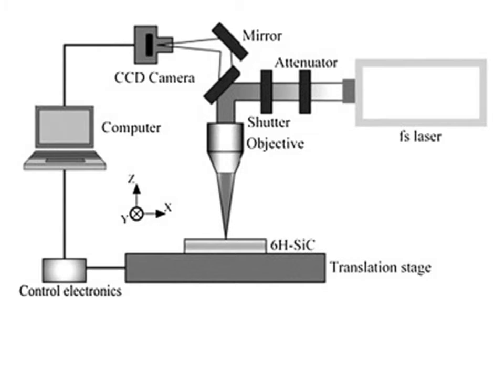Here I would like to show you a schematic diagram, some of these diagrams, at least a smaller version of this diagram, you'll have to learn. So here I have shown a femtosecond laser which is used for material processing, but what type of laser you will use depends on what type of material you want to process. So here I have just shown you a femtosecond laser because it is capable of delivering high energy pulses, and that laser is first passing through an attenuator, and that attenuator is actually a device which will reduce the power of the laser which is passing through it.